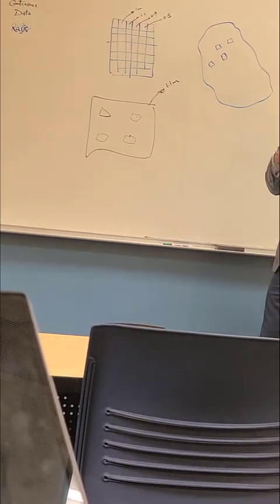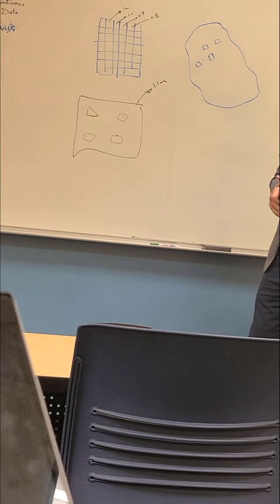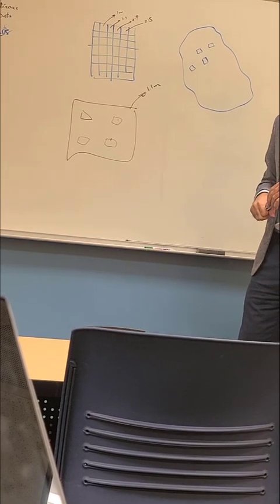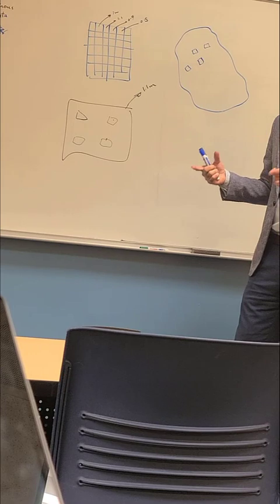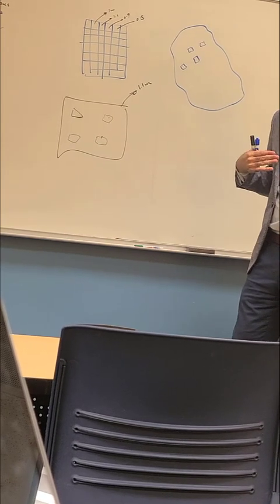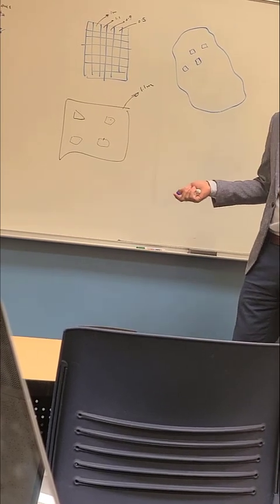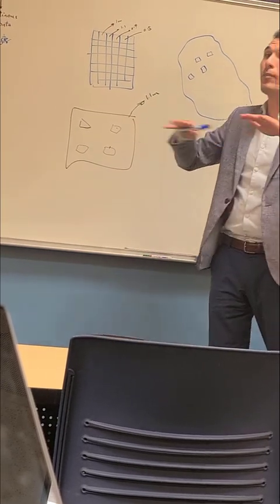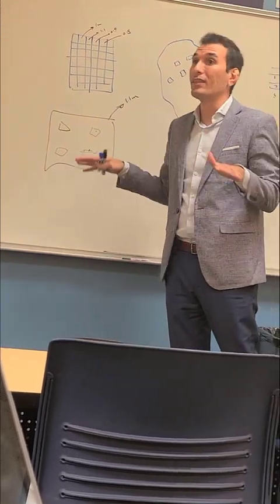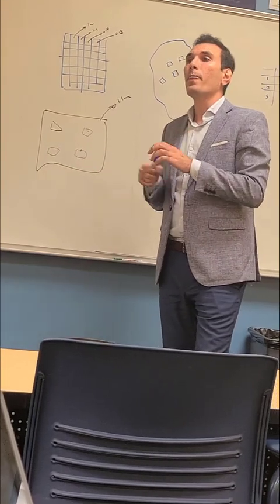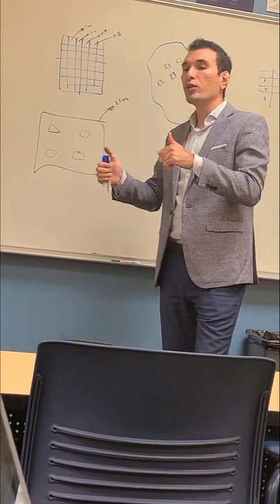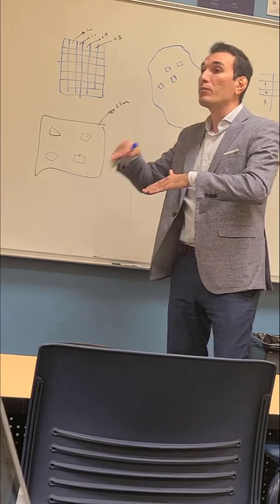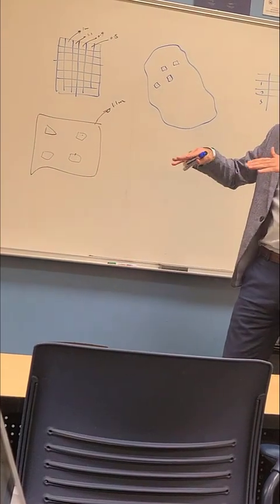I have been working with Mexico Beach, Florida, and I have a wind hazard map. The pixel size that I got from the coastal guys is 1 kilometer by 1 kilometer. And Mexico Beach is actually 1 kilometer by 1 kilometer. So all the buildings within Mexico Beach had the same wind speed. Why? Because the coastal guys who do coastal analysis of hurricanes model the hurricane in the ocean.